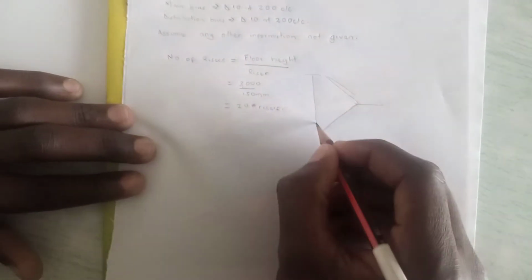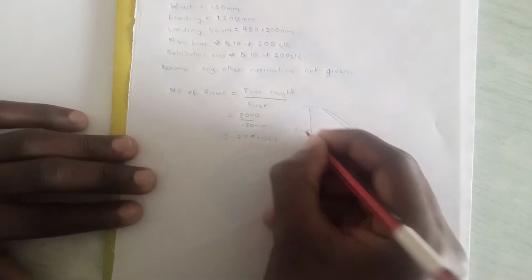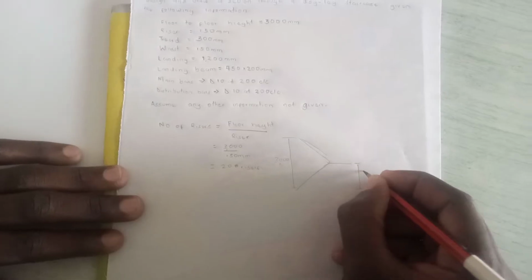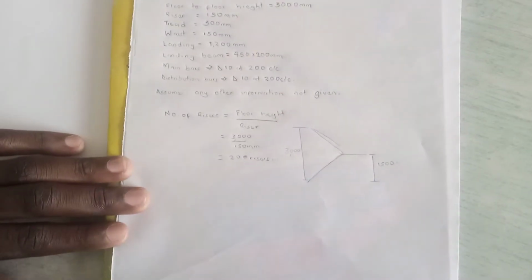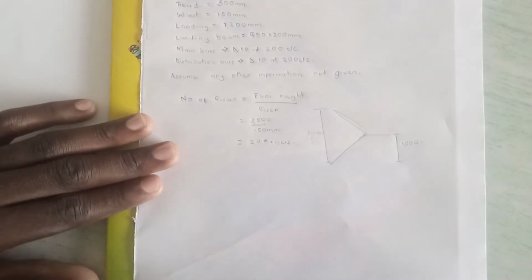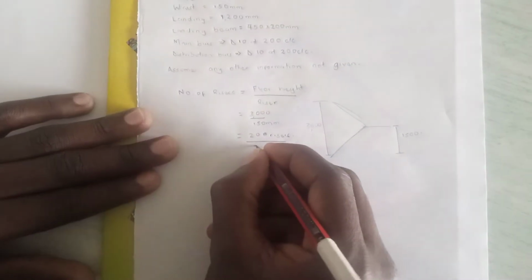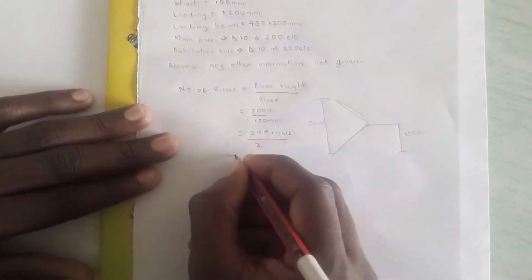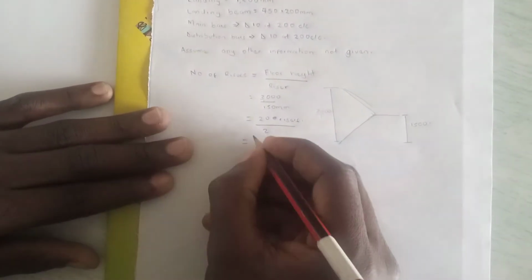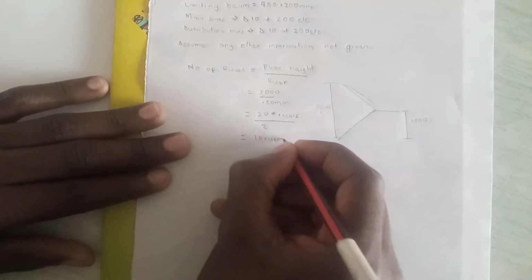The height I've used is 3000 millimeters, so we can divide this height by 2 and get the height from the floor to the top of the landing, which is going to be 1500 millimeters. A person can decide to use that or go this other way. So I'm going to divide the number of risers by 2 to get how many risers should be in each flight. So this one will be 10 risers for each flight.